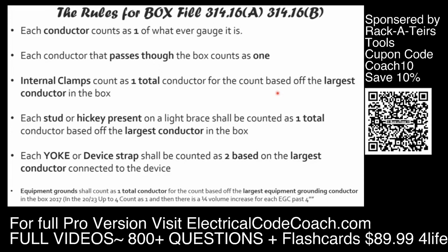Now in the 2020 and in the 2023, it's a little bit different. Up to the first 4 conductors, it's going to count as 1. Then for every one that is past 4, you're going to increase it by a 1/4 inch volume. And we're going to do some practice questions with these. Just let that soak in, and when we get to the practice questions, we're going to expound on it more. If you're still on the 2017, when I come to this part of the lesson today, I want you to just fast forward through it.